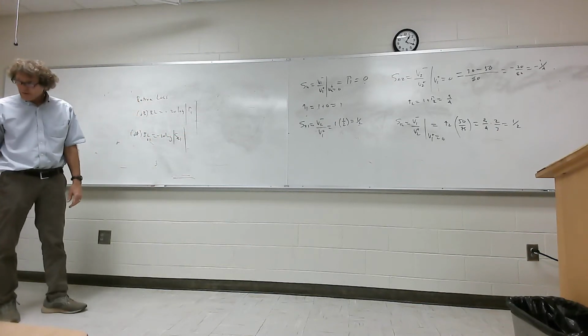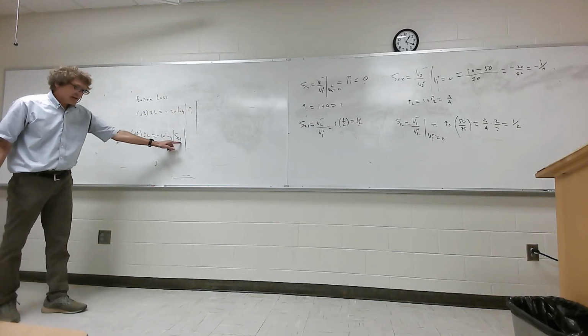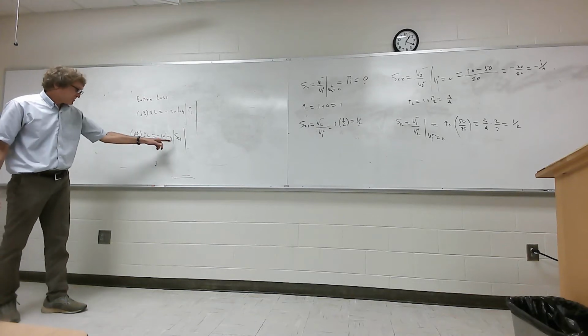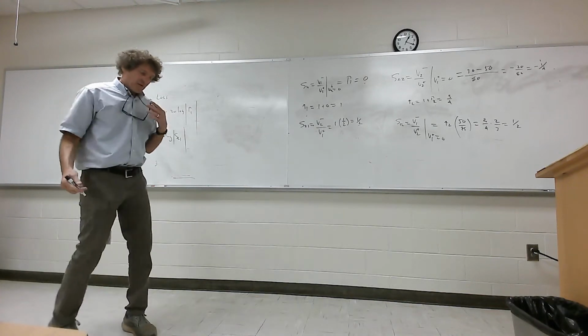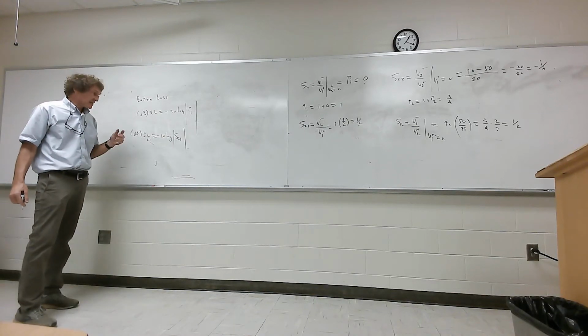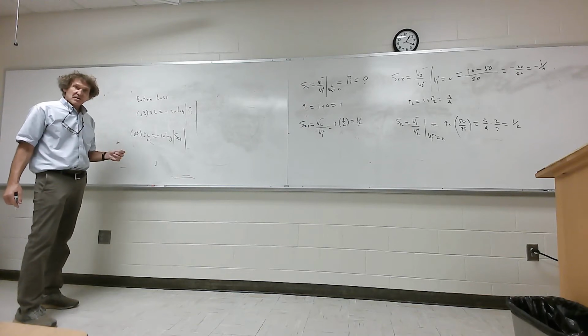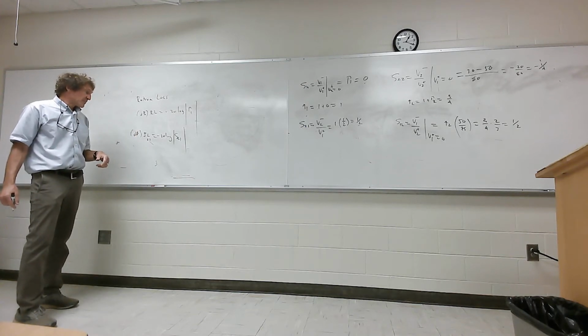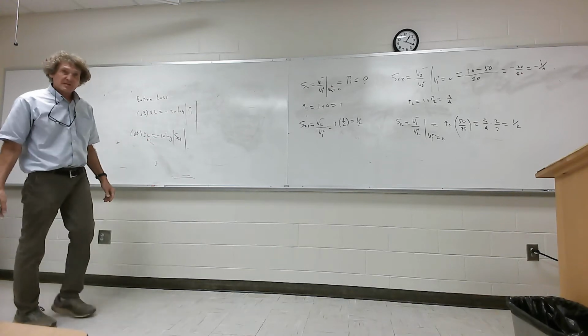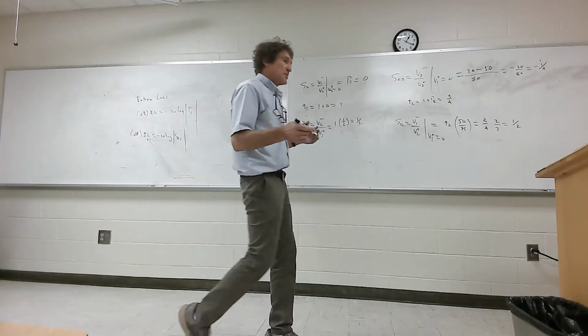Y'all follow me? If you wanted the insertion loss 2,1, you simply put S21 in there, take the magnitude of it, the log of it, and put minus 20 in front of it. And you have the insertion loss. If you wanted the 1,2, then you just put S12 here, take minus 20 times the log of it. That's just concepts, but they're used all the time.